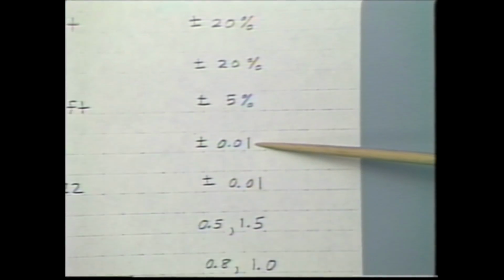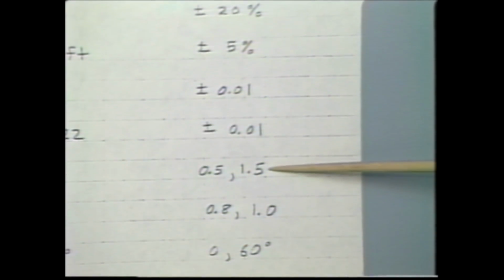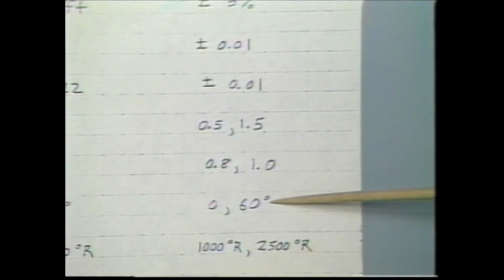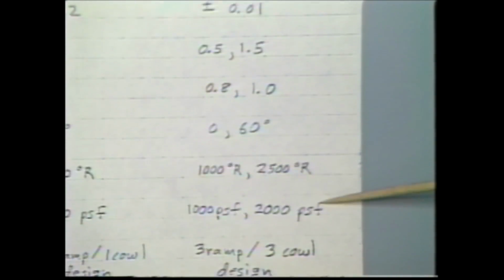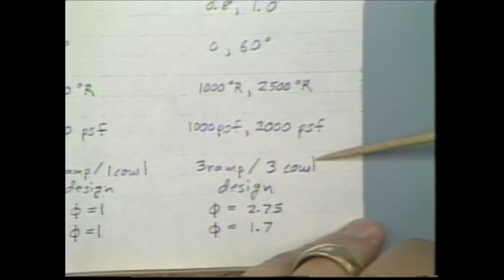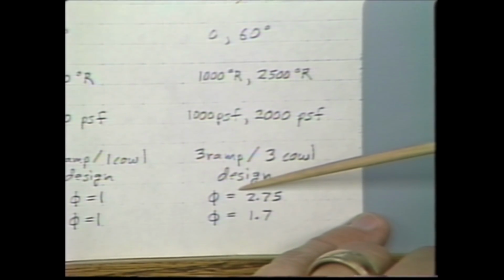The inlet efficiency, just independently varying, doing what-ifs. What if you could increase or decrease the inlet efficiency by 1%, or the nozzle efficiency, what would it do? Or the fuel equivalence ratio you had to operate at, or the combustion efficiency achieved. Different fuel injection angles, fuel temperatures, the dynamic pressure that you're flying at, a different inlet design. Or these last two were very important, thermally balanced.